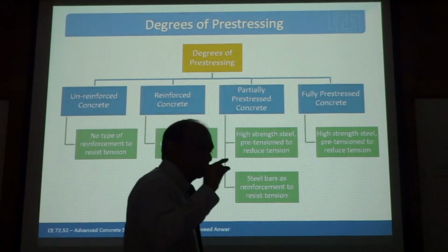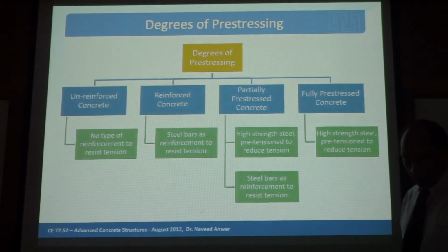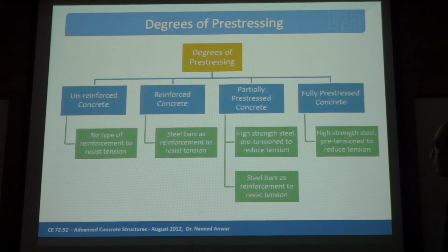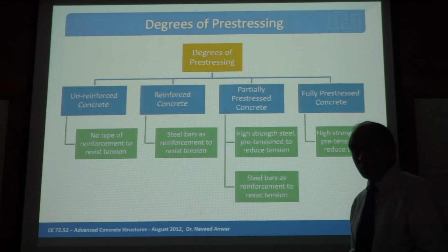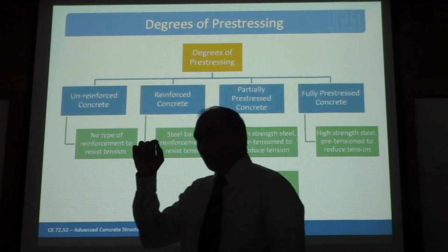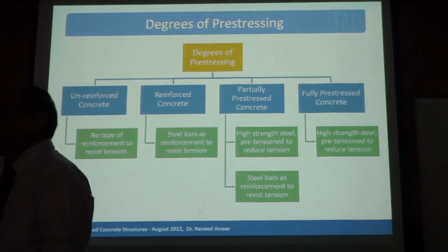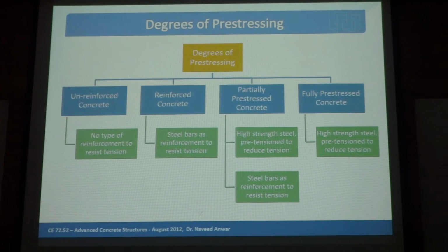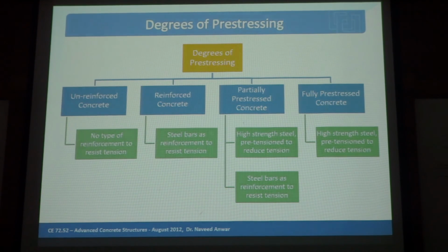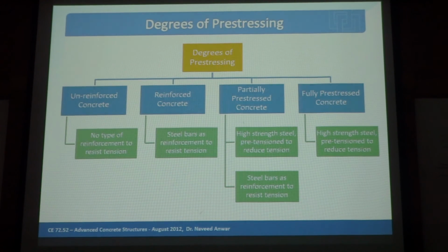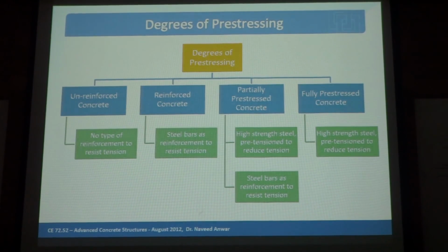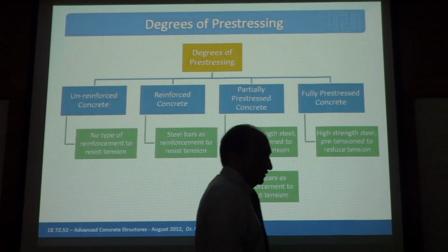But we allow some form of tension here. Because we are using very high strength concrete, the allowable tension is quite high, it's not so small. Because for pre-stress we normally use high strength concrete. And f'c, as you know, the tension capacity is related to the square root of the compression capacity, correct? So we still get quite a substantial tension capacity that we can utilize.